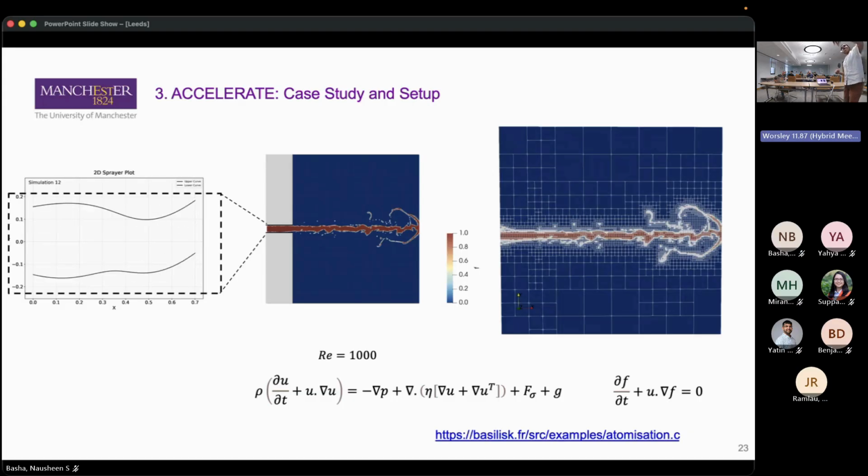What you have here is an adaptive mesh. It is called adaptive grid refinement here, which is useful to capture the filaments and the droplets associated with those. Imagine if you didn't have this adaptive mesh and you had to mesh the whole geometry; it would be super expensive. So it has this adaptive mesh feature to capture these instabilities and the finer features.